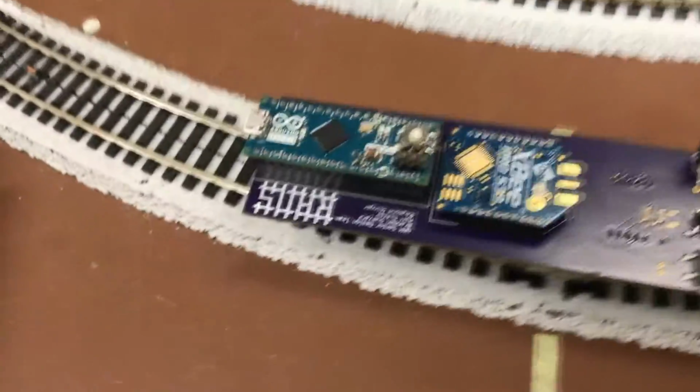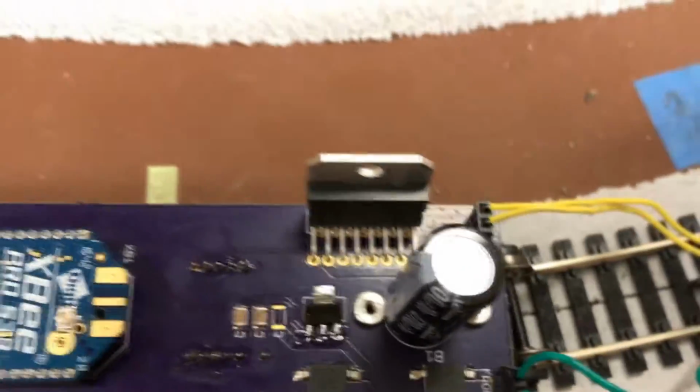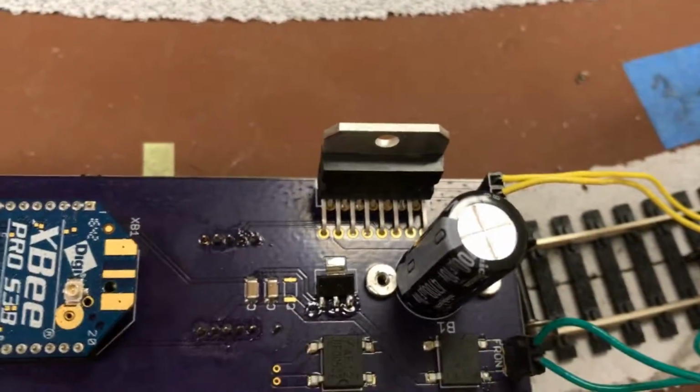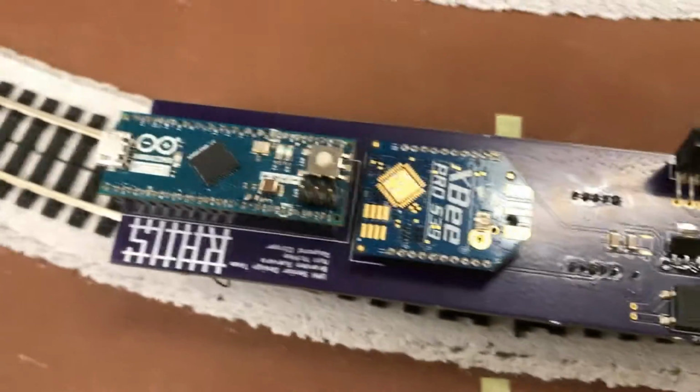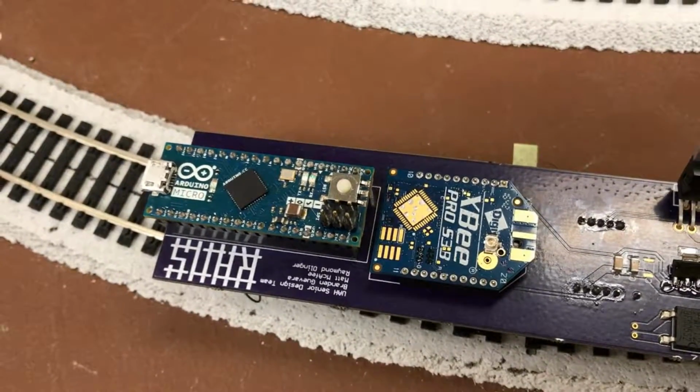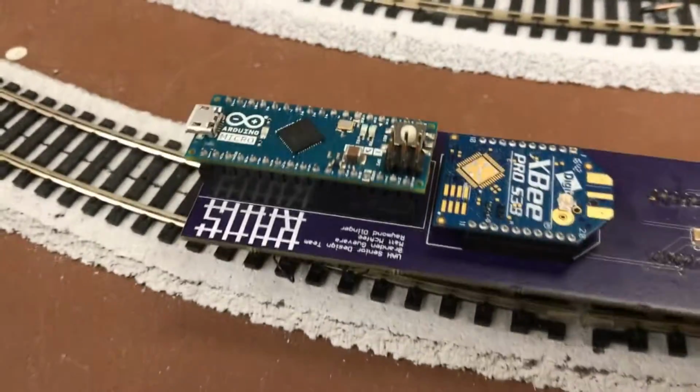Arduino Micro is our main control system for our design. The motor driver will modify the DC signal to a suitable pulse width modulated signal specified by the Arduino that will power the motor directly. The Arduino controls 3 pins on this unit to determine speed and direction of the motor.